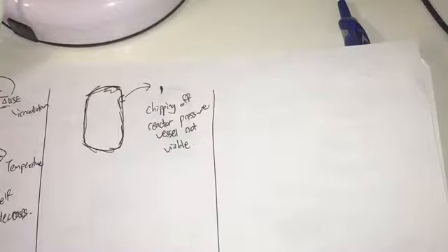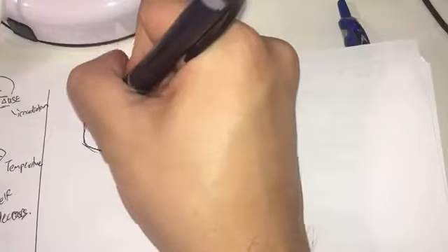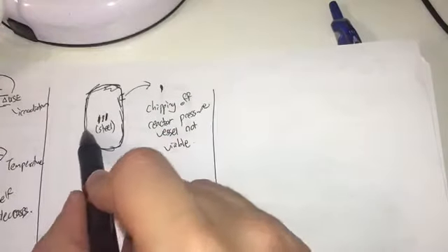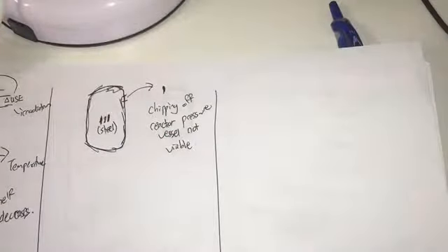So what do you do instead? The normal practice is to have a few pieces of steel made of the same material as the reactor pressure vessel, with the same microstructure and everything. They put a few lumps of steel into the reactor core where the neutron flux is the most.